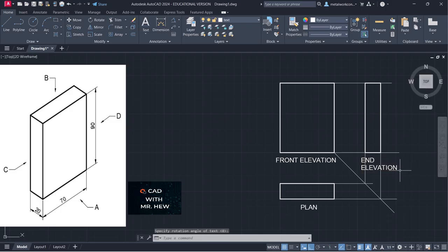So that would have completed our drawing there, okay? All right, we're gonna do the same thing on the other side. So what we're gonna do, we're gonna draw a 45-degree line to the T-square, to the horizontal. On our AutoCAD, the angle would actually be 225 degrees, because the AutoCAD is measuring from this way coming around in an anti-clockwise direction, okay? With this line being the zero line. So from this line measuring an anti-clockwise measurement, that is the angle. That is why I got 225. So I added 45 degrees to 180 degrees, and that's why I got 225 degrees.